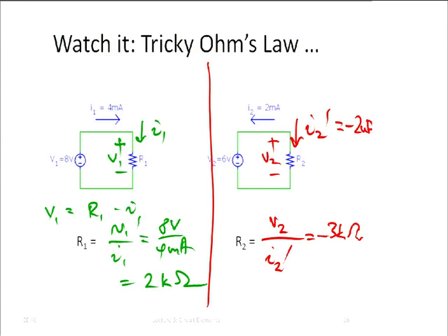So then how could you get over that? How could you fix this problem that the clock stops after tenths of a second all the time? That would be very painful. Okay, fine. But what is that mechanism? You need a mechanism that supplies the power that the stupid resistor we didn't want, or the friction in the grandfather clock, always dissipates. You need that, right? In the grandfather clock, it's the big weights. In the electronic circuit, it's a negative resistor.